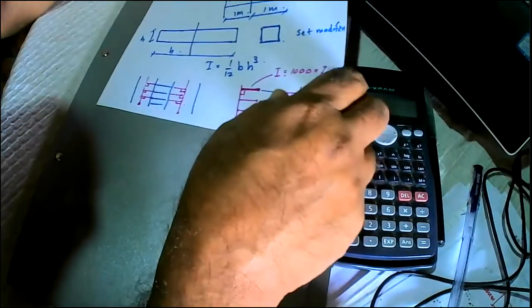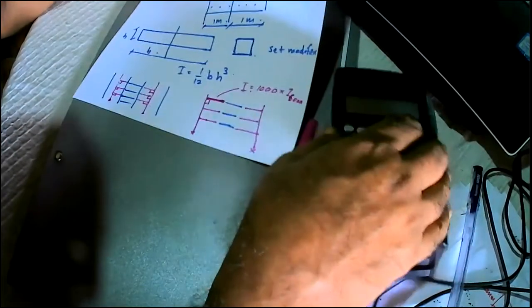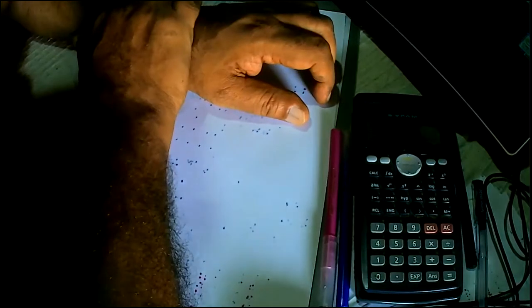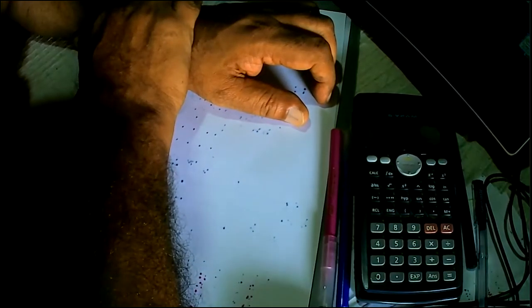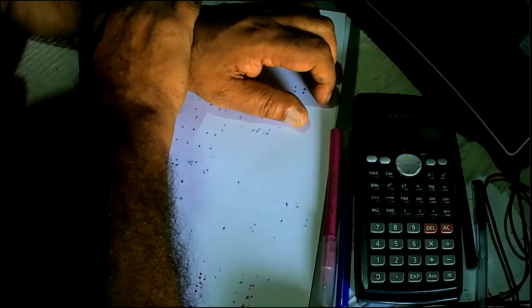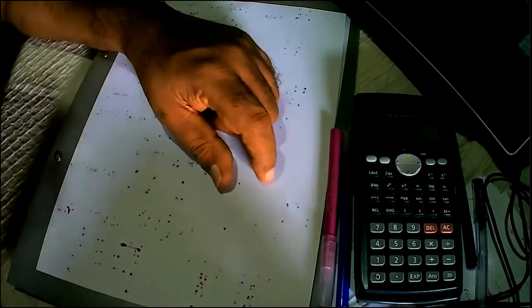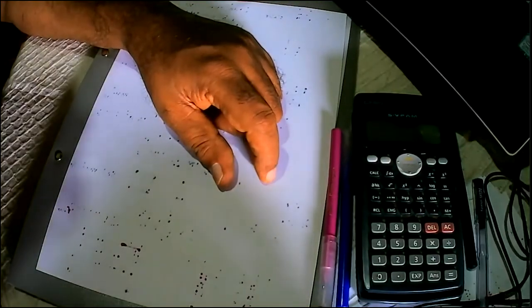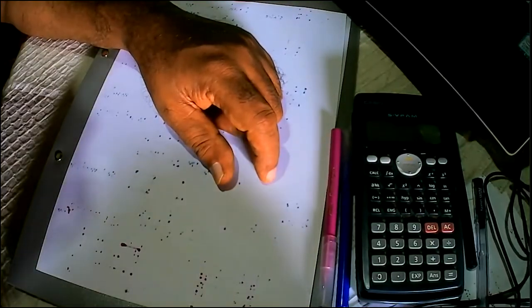So these are some of the modeling techniques. Sometimes you find that these are useful, but to a lesser degree these days, because in most of the programs we have shell elements and we can easily model a shear wall with its actual size.